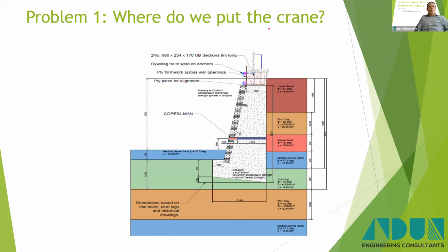If you build a tower of wooden blocks, they're very easy to push over. If you build a tower of wooden blocks and you put a load on top of it, they become very difficult to push over. And that's exactly the principle we used here to demonstrate that the wall itself was stable and this load is beneficial. And because of the way the wall was constructed, we were quite happy that there was sufficient load spread at the base of the wall that this 165 ton outrigger load at the top here wouldn't cause any bearing failure.